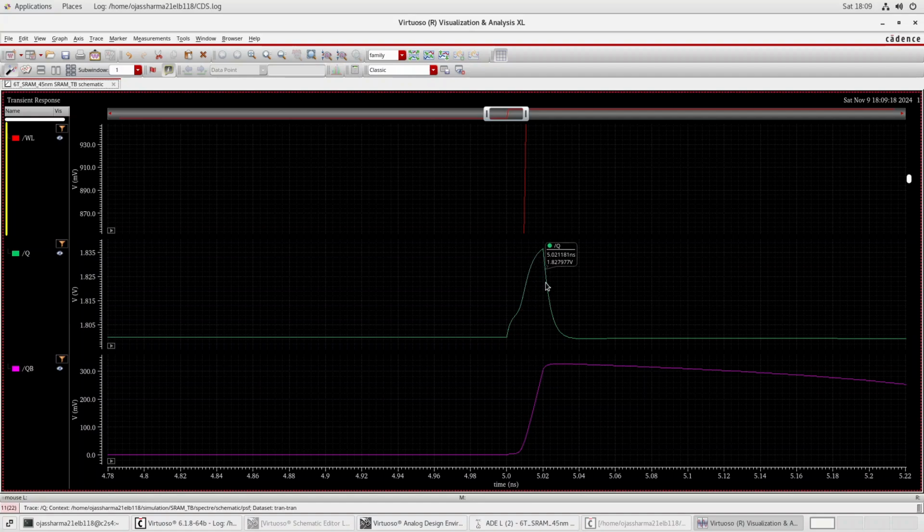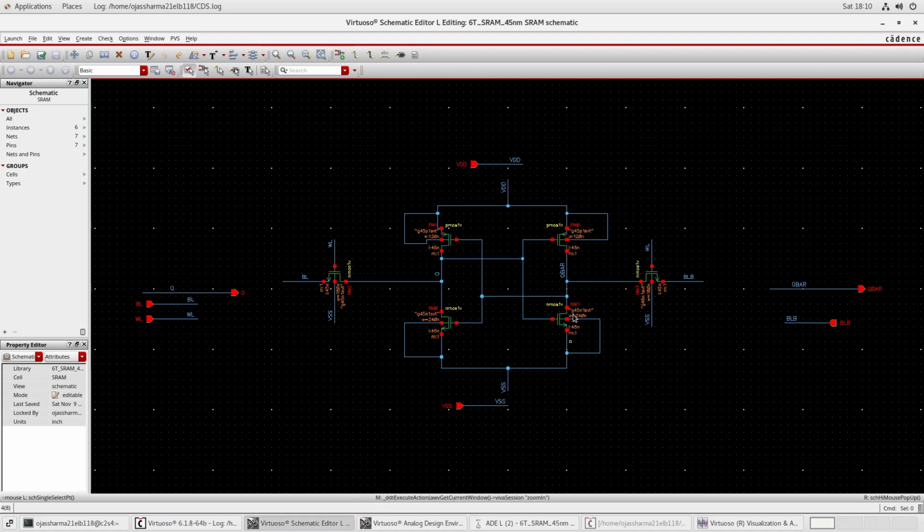Now this dip disturbance curve can be lowered down by increasing the width of the NMOS which has been used for the decoupling of the inverters at the lower side, increasing the width of the inverters which are decoupled together, as in the schematic. I'll show you once again. I'm talking about these two inverters. This can be lowered down by using this.